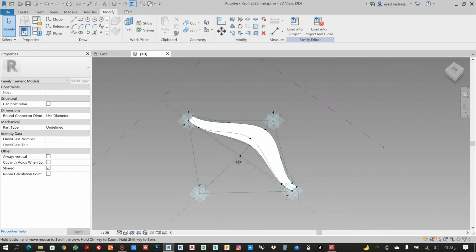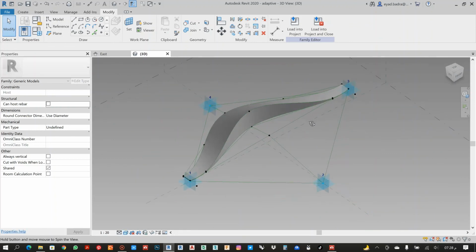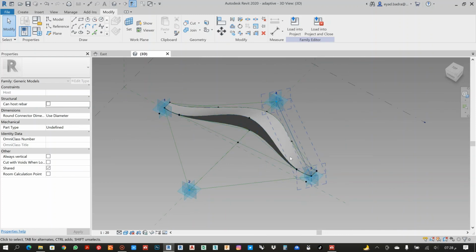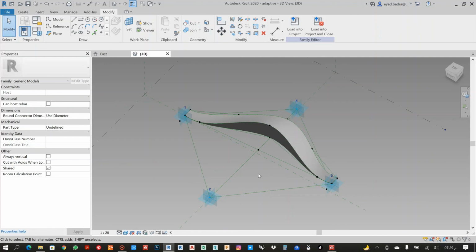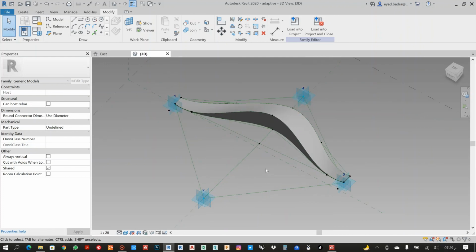So in this case, we already made our shape for the eye. We will do the same task that we did in this triangle in this other triangle to make the other part of this eye, and then it will be almost ready to make our adaptive component, put it on our 1-point curtain panel and make our shape.